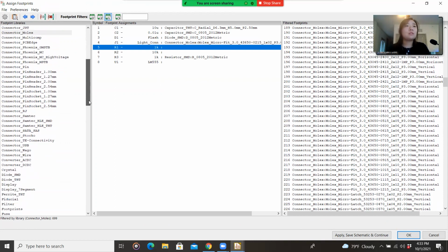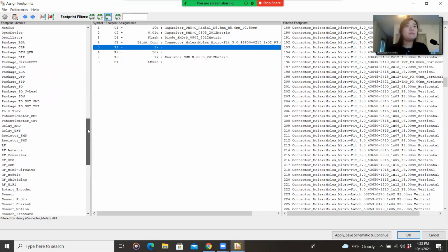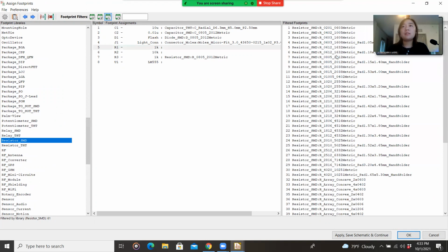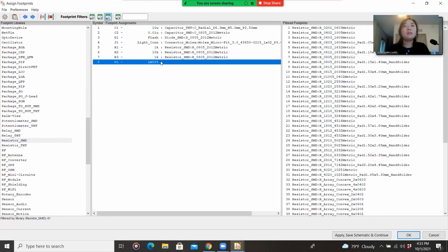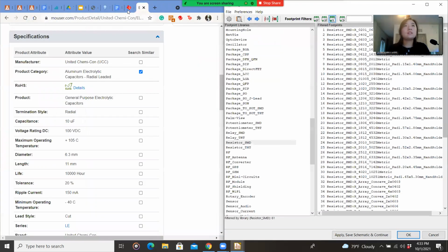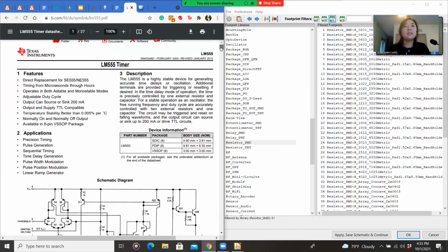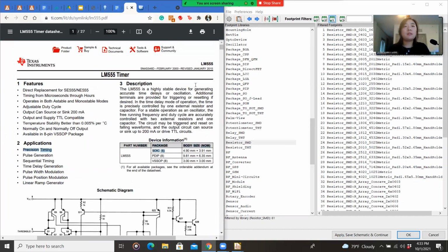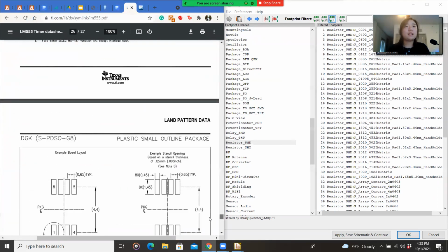And then we go back to populating the resistors. So we get 0805, 0805, and then, okay, what package do we want for this? Notice that sometimes KiCAD provides the packages, but in this case, it does not. So we can see the different packages it has here.